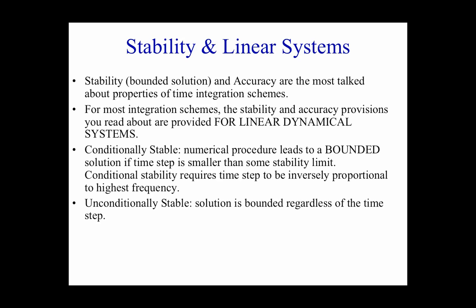If you go to a textbook and look at the stability criteria for these integration schemes, they're all based on linear elastic systems. Okay? They only apply to linear systems. Everybody uses them in nonlinear systems. Those stability results have been proven for elastic systems. The same things do not work when you go to nonlinear.